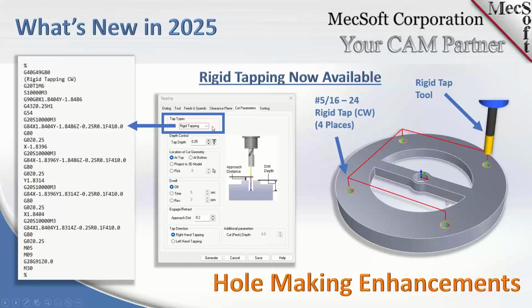If you're unfamiliar with rigid tapping versus regular tapping, the difference is in the tool itself. In rigid tapping, the tool is rigid. In other words, the holder, the thread, everything is one rigid unit. The movement of the threading, the cut feed, and the Z-dip is all controlled in the spindle and in the cut parameters that you're outputting.